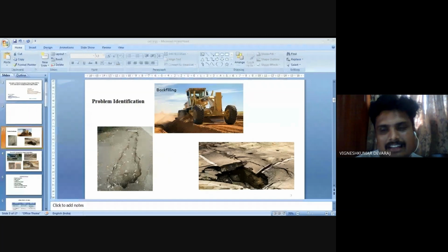Quarry hydrocyclone waste is fine material removed from the manufacturing process of quarry products like fine aggregate and coarse aggregate. We remove these fine particles because they reduce the workability and strength of the concrete. That's why it is removed and dumped in huge quantities in every quarry. Nearly 620 million tons of this waste are dumped in every quarry.